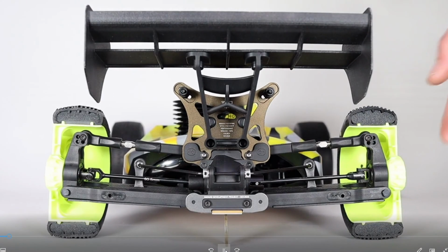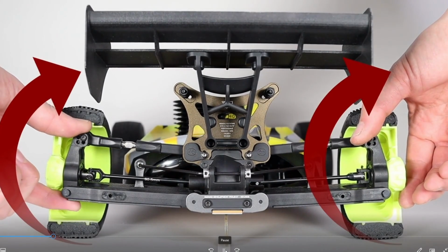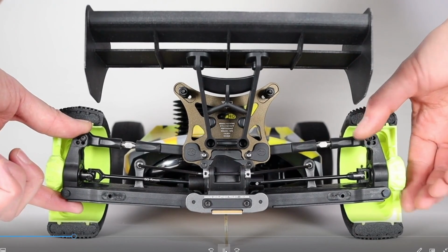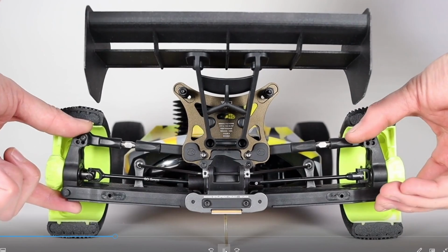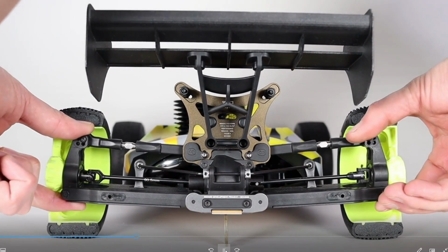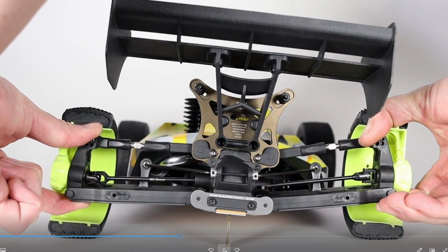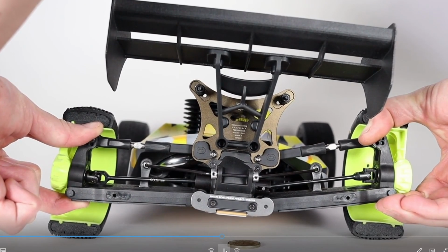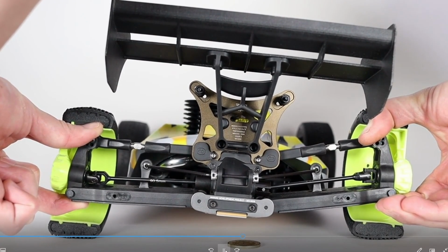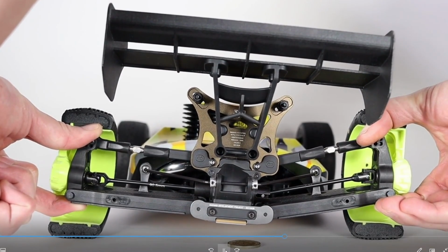And now what I'll do is I'll twist the hubs as if the car was in a corner. I can't twist the wheels because they're so flexible. So I'm going to twist the hubs. What do you think will happen when the coin drops? There you go. The jacking force is holding the chassis up. If I reduce tension, the chassis drops.